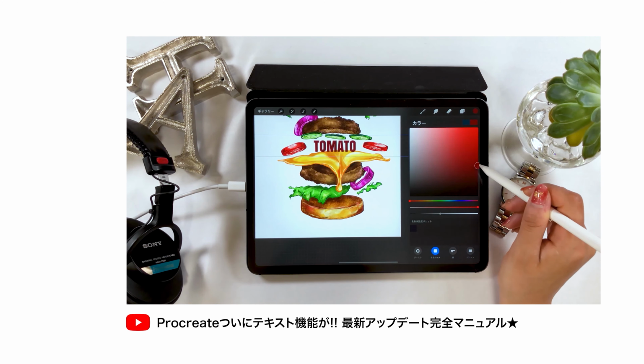We'll use a special function first by selecting the text with the arrow icon. On the panel appearing below, click on Freeform. This allows you to resize the text regardless of the original length-to-width ratio. So let's try stretching the text vertically.